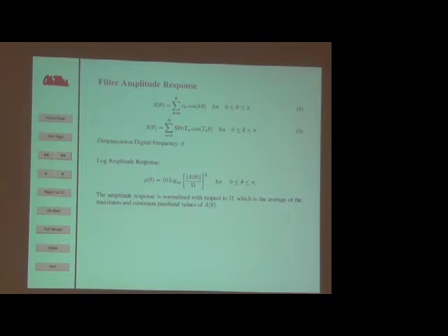Okay, what I'd like to design is the amplitude response. I can write the amplitude response in equation 8 for the coefficients of the standard sort of filter, but I can also write it in terms of the signed power of 2 coefficients. So here, if you will, is the model. This is the thing I'm trying to design for. And here, theta is dimensionless digital frequency. Essentially my sampling period is 1, so the maximum frequency is pi.